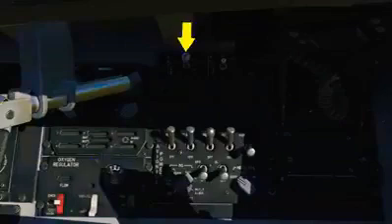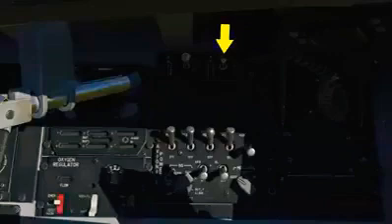The secure voice panel is something we hope to implement at a later point once we add integrated voice over IP into DCS World. The anti-ice system prevents ice buildup on the probes and in the engine. It is activated by placing the switch in the on position, but it will also be set to the automatic and will automatically turn on when ice is detected. Off disables the system. The 2 switches of the antenna select panel allow you to select the upper, both, or lower antennas for the IFF and UHF radios.